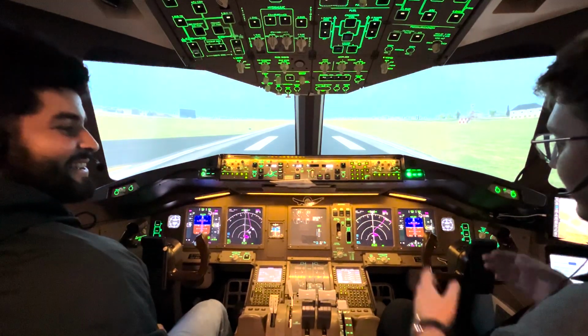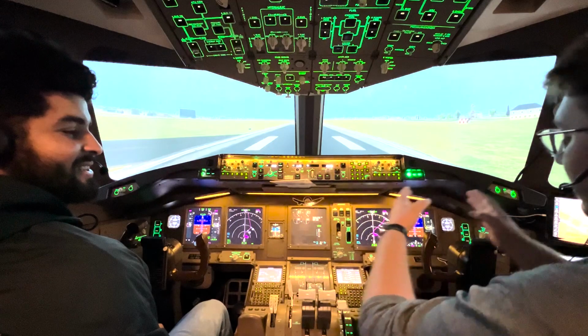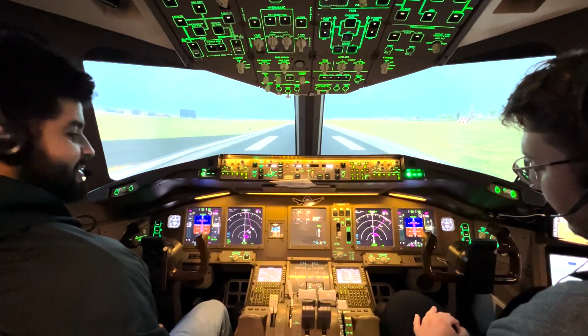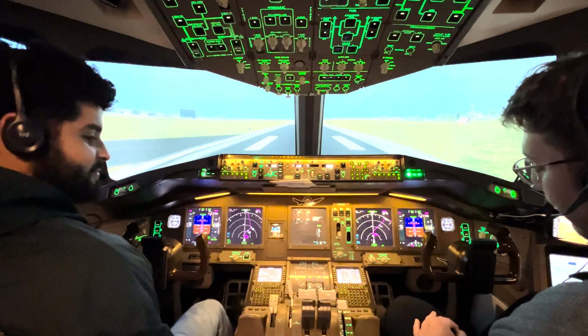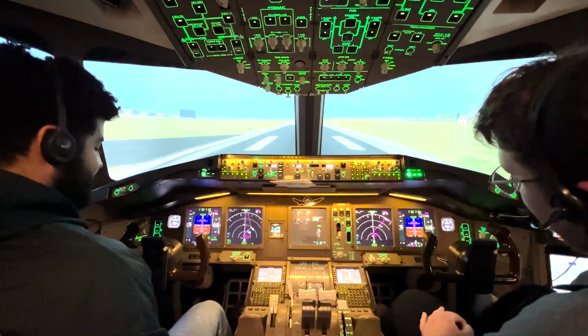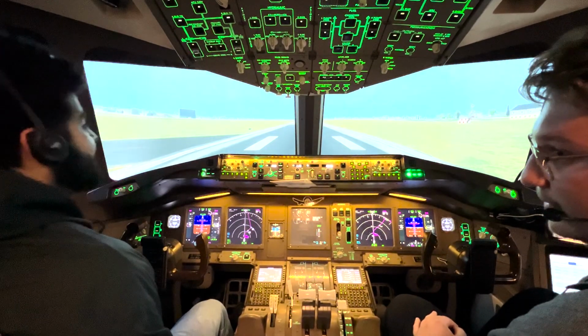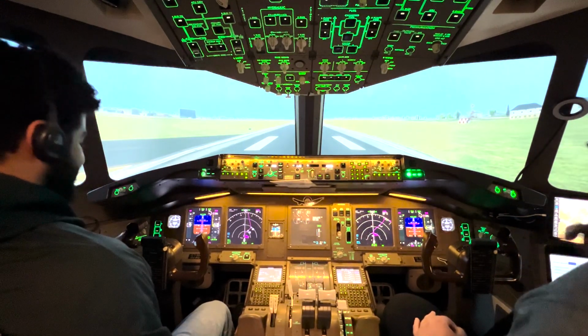When we're on the ground, if you notice the plane is going off to the left or to the right too much, then you're going to use your rudder pedals. You always want to keep the toes of your feet on the bottom end of the rudder pedals. You never want to keep your full foot on it. Yeah, I get it, because we don't want to apply brakes by accident. Exactly. Okay, go ahead.